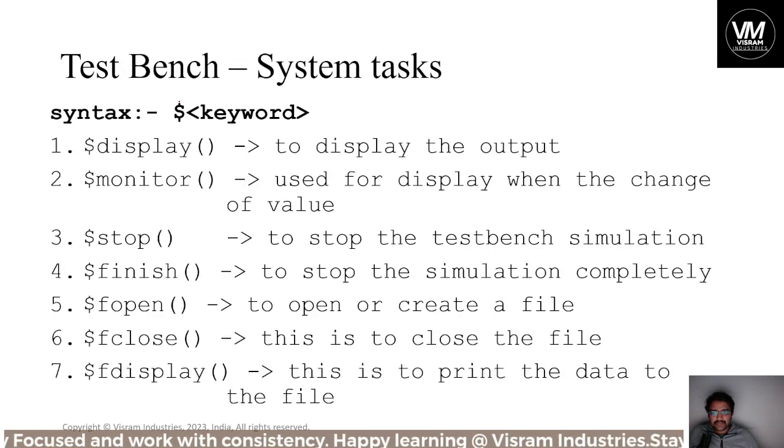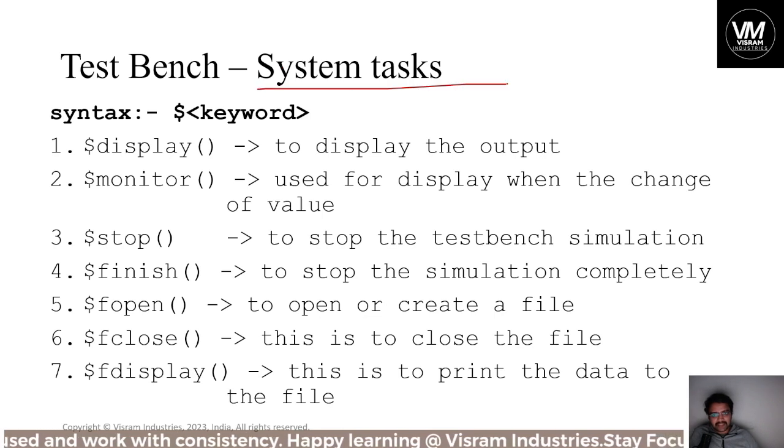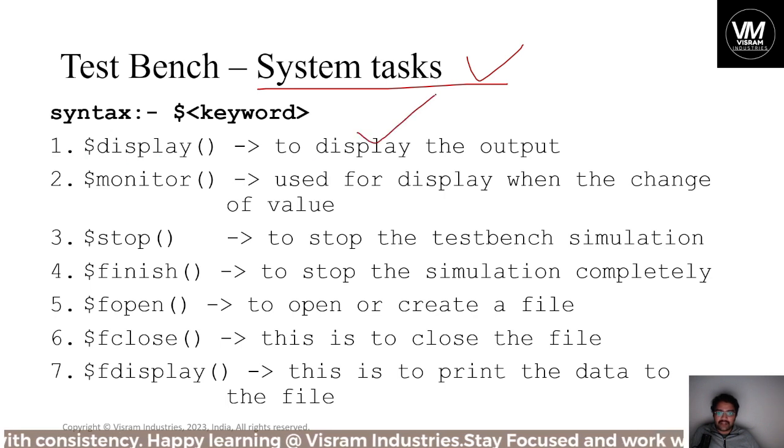Some of the system tasks you should know while writing Verilog HDL are $display, which is used to display output. For example, you can consider this as the printf function in C programming. And $monitor, you can consider it as used for display when the value changes.